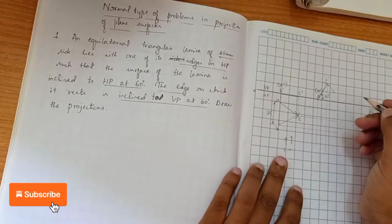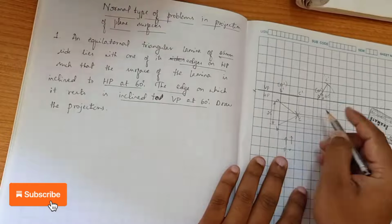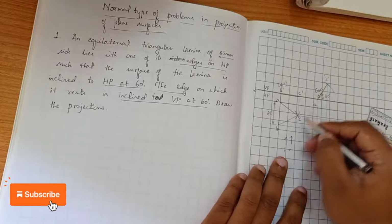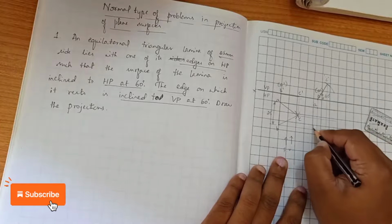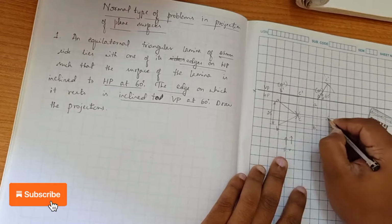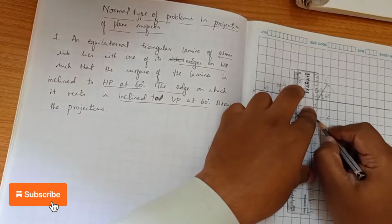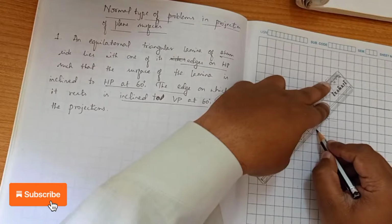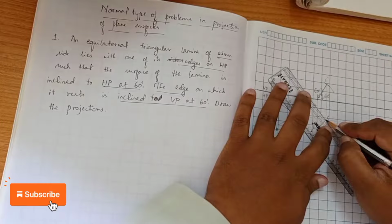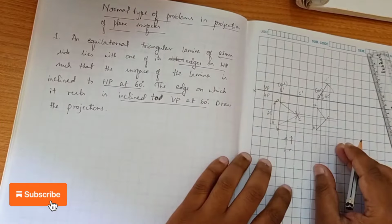Now we have to see where the points merge. From A dash there is a projection line, and A, these two are merging at this point. This is our A point. Similarly B dash and B, it is merging exactly here. This is B. Similarly C and C dash, it is merging here. So now we can join these to construct the inclined second position top view. So now we are done with the inclined second position top view.